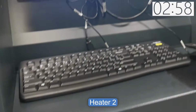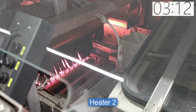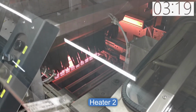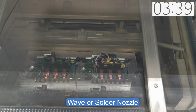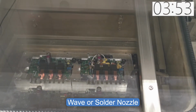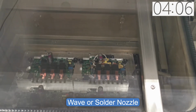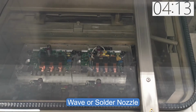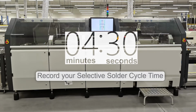Most, if not all, selective solder machines will not convey the product continuously or uninterrupted all the way through the selective solder process. At some point, the board will stop at the solder pot area for selective wave soldering. In some selective solder machines, the board may come to a stop at more than one point during the process. Therefore, we cannot enter a conveyor speed in the Kick software as we normally would with a true continuous conveyor speed application. Record your selective solder cycle time for future software configuration.